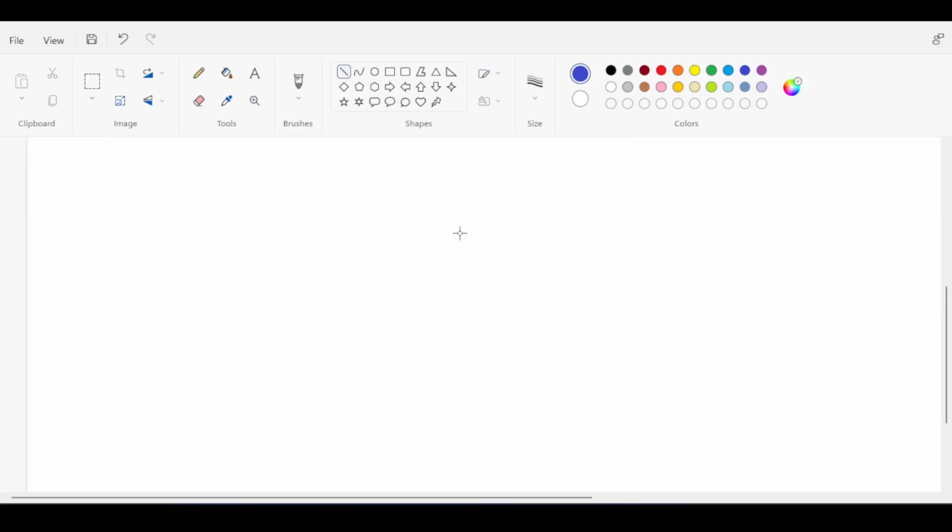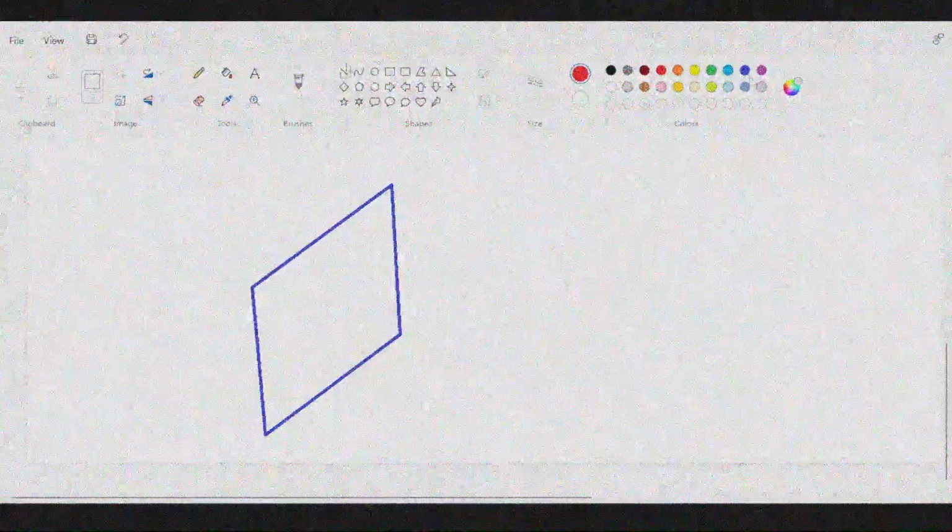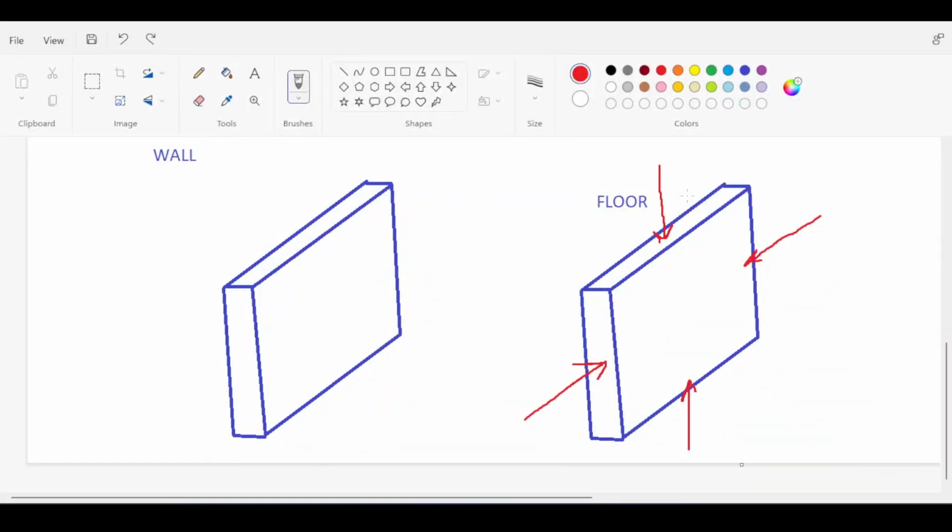What do I mean by this? Let me draw the wall in 3D. Okay, so the difference between the floor and the wall is that the floor is being designed having in mind the following forces. The forces in Y as normal forces, the forces in X as normal forces, which will cause compression and tension on the wall, requiring steel. Of course, those axial forces will provide steel equally in the outside face and the inside face, so basically on both sides.